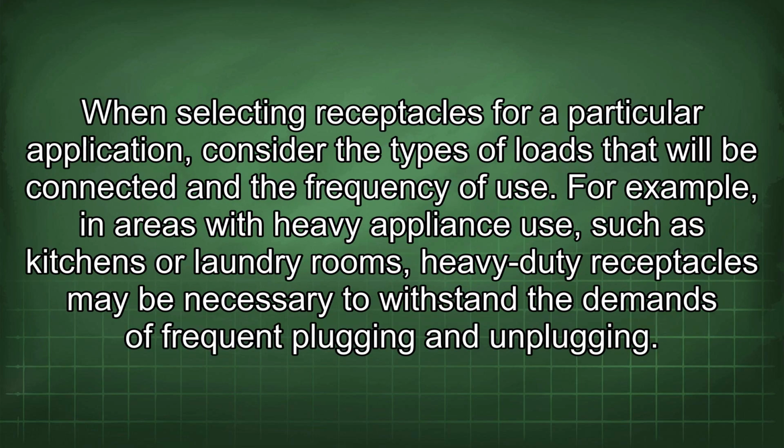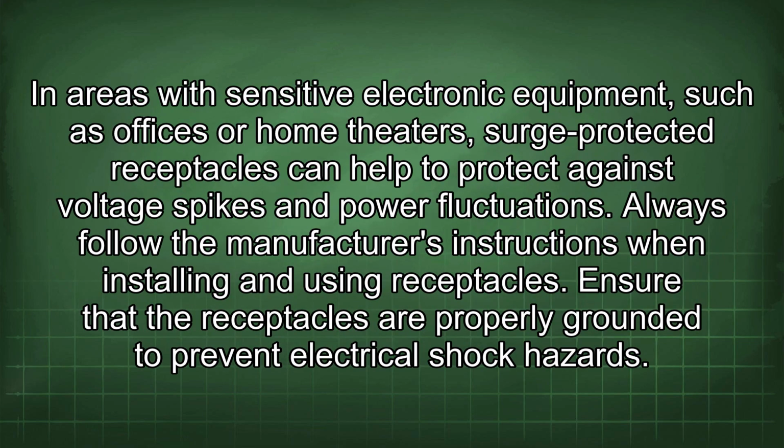When selecting receptacles for a particular application, consider the types of loads that will be connected and the frequency of use. For example, in areas with heavy appliance use, such as kitchens or laundry rooms, heavy-duty receptacles may be necessary to withstand the demands of frequent plugging and unplugging. In areas with sensitive electronic equipment, such as offices or home theaters, surge-protected receptacles can help to protect against voltage spikes and power fluctuations. Always follow the manufacturer's instructions when installing and using receptacles.